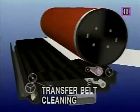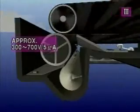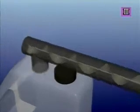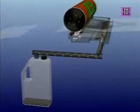Paper dust and toner adhering to the transfer belt are scraped off by the cleaning brush, which is biased at 300 to 700 volts by a current of 5 microamperes, and the cleaning blade, and then collected into the toner box by the recovery auger. The toner adhering to the cleaning brush is scraped off by the flicker.